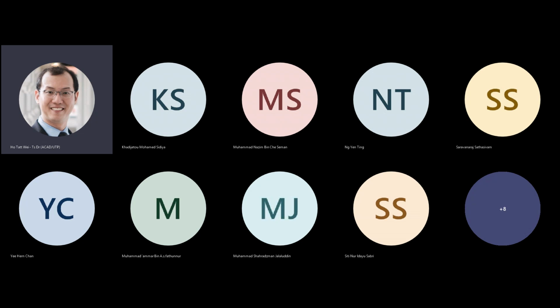This is my control, and this is my control bar, right? So the only way I can send I1 to this output is if C is a logic 1. If C is a logic 0, this AND gate is effectively frozen, because it's only going to hold a 0 at the output as long as C is 0.